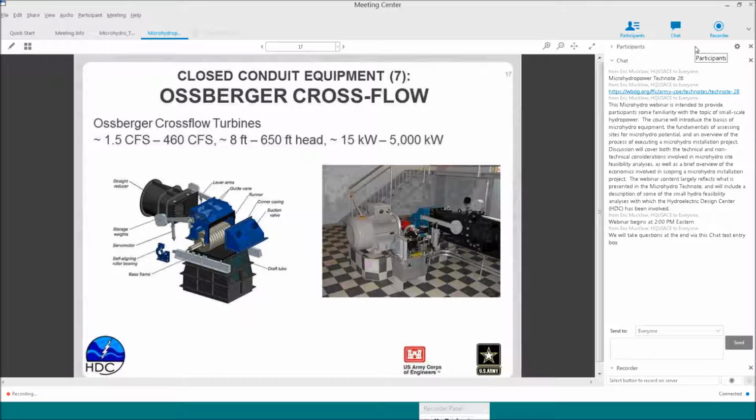And just to familiarize you with the equipment you see in the picture here, again, the depiction on the left is just reversed from what you see on the right. This actual installation on the right, I'm not sure the actual size, but would guess that it's within the microhydro range. And so it's fed by a penstock. And this arm here is part of the mechanism to open or close the guide vanes, which controls the flow through the turbine. There's the generator unit at the left, and then the governor and control mechanism in front there.